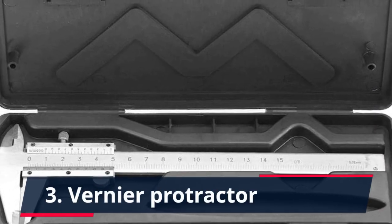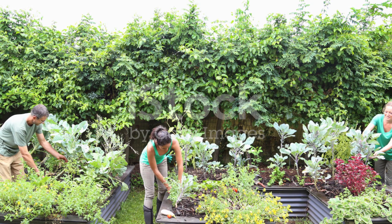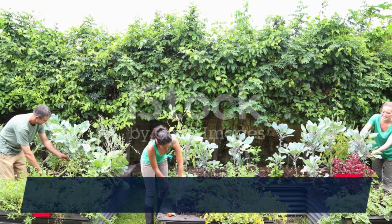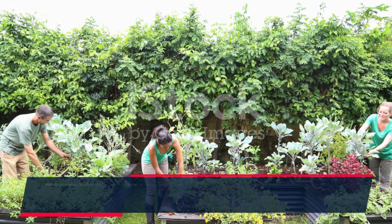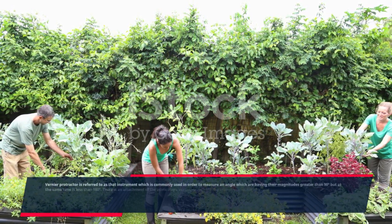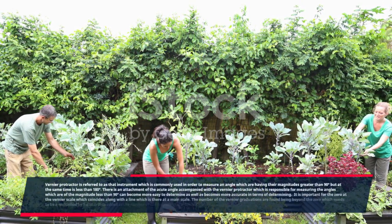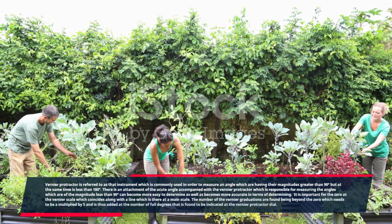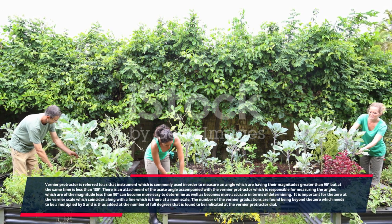3. Vernier protractor. A vernier protractor is an instrument commonly used to measure angles having magnitudes greater than 90 degrees but less than 180 degrees. An acute angle attachment accompanies the vernier protractor, which makes measuring angles of magnitude less than 90 degrees easier as well as more accurate.